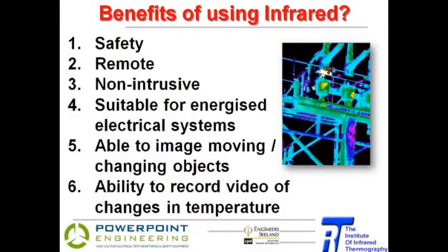We can record video of changes of temperature, which again is very useful. The survey that I did in the wind turbine, we set a camera up and recorded the splices coming down from the wind turbine over a 24-hour period. So we could see, as the turbine ramped up to full load, how the temperature changed on those splices. You couldn't do that any other way.